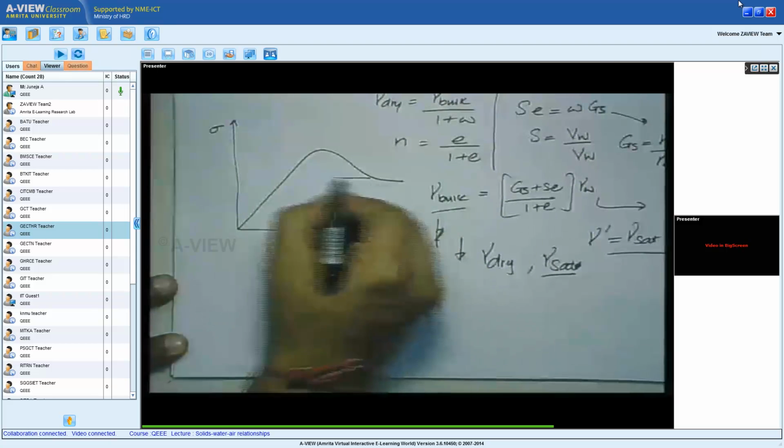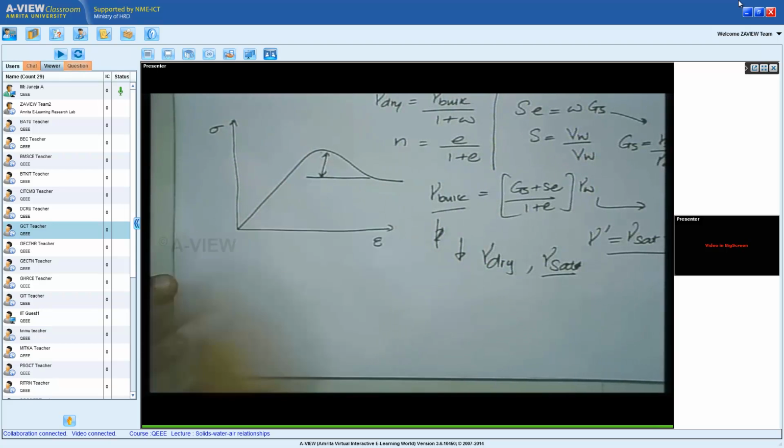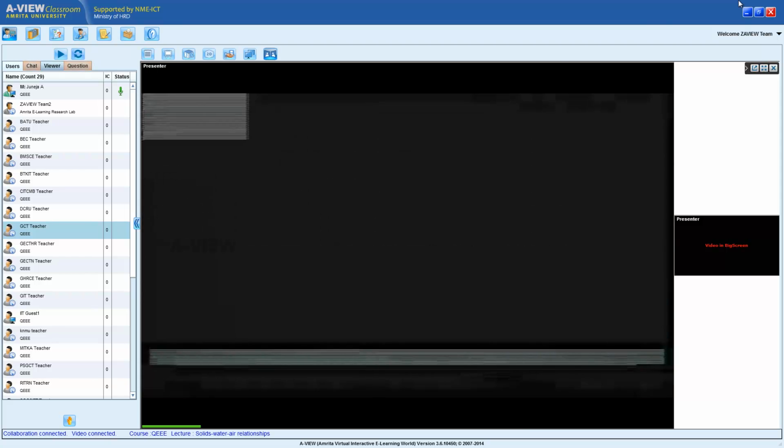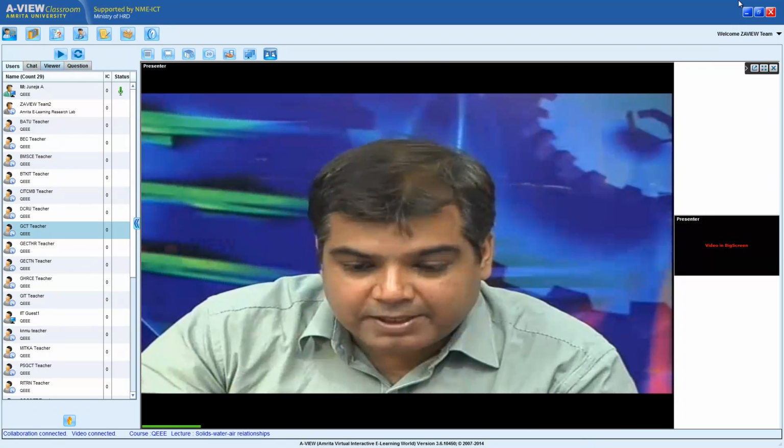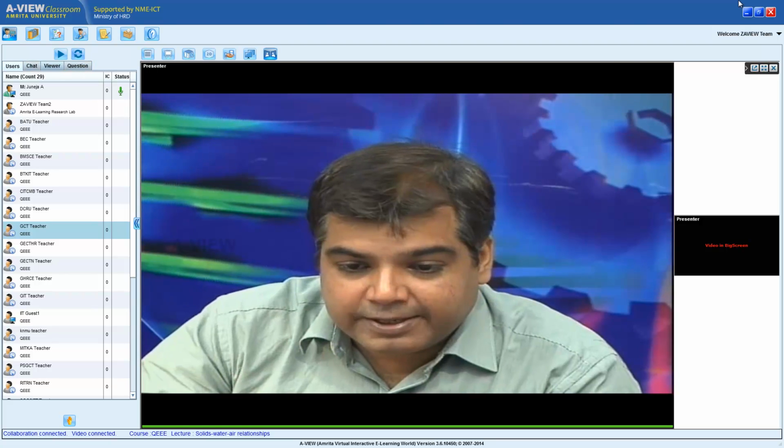Now the size of the hump is governed by the angularity of the particle. The more angular the particle, the more they control the size of the hump. With denser particles, of course, the size of the hump is also governed, but what we see is that density is one factor, but the interlocking also plays a greater role in the strength characteristics.